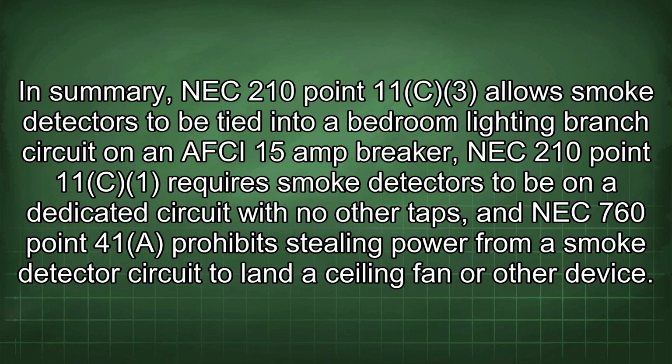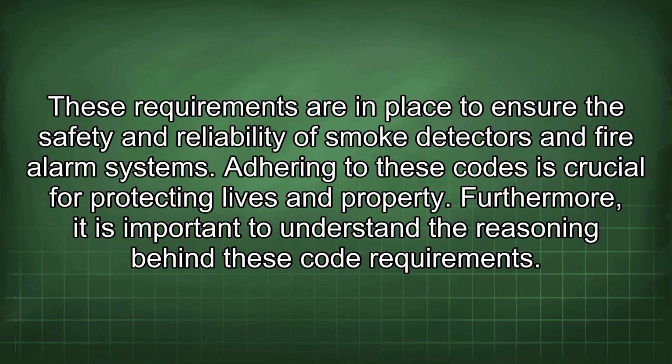In summary, NEC 210.11c3 allows smoke detectors to be tied into a bedroom lighting branch circuit on an AFCI 15 amp breaker. NEC 210.11 c1 requires smoke detectors to be on a dedicated circuit with no other taps, and NEC 760.41 prohibits stealing power from a smoke detector circuit to land a ceiling fan or other device. These requirements are in place to ensure the safety and reliability of smoke detectors and fire alarm systems. Adhering to these codes is crucial for protecting lives and property.